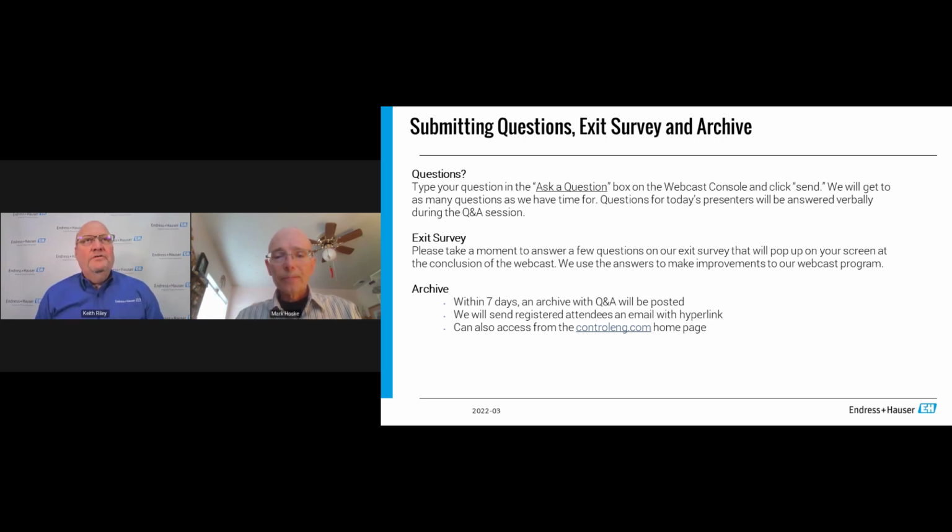I'm better equipped to go back to that Liquifont example, to reiterate that by using verification, the customers we've talked to indicate that by the time you take into account downtime and reduced risk, because remember, every time you remove an instrument from the process, you're probably also disconnecting it from your control loop. So every time you handle it, you risk damage to the device, which is a potential additional cost. The same thing goes for rewiring. Did somebody damage the wiring?